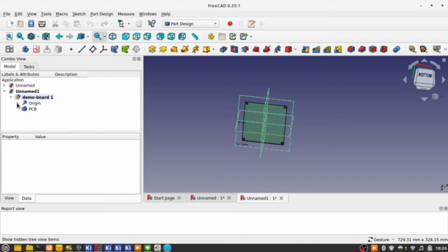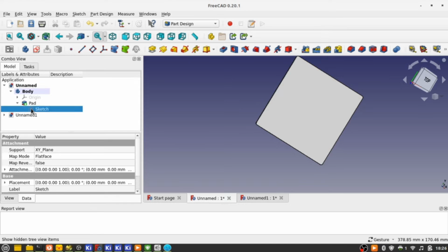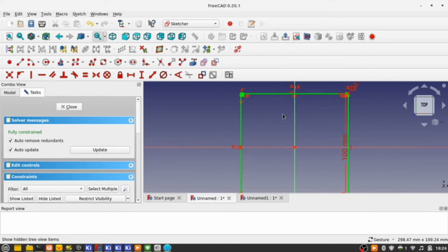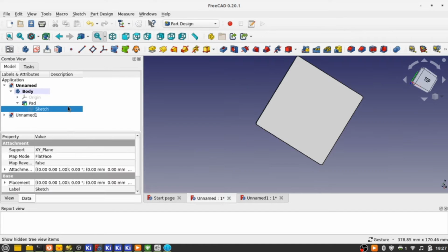Here is an example project. That's actually the imported PCB. So here's the sketch. It's pretty easy. You make the sketch of the rounded rectangle in FreeCAD, then you import it as an SVG into KiCAD, save it as a part, and then use it just as you would any other part in your library.